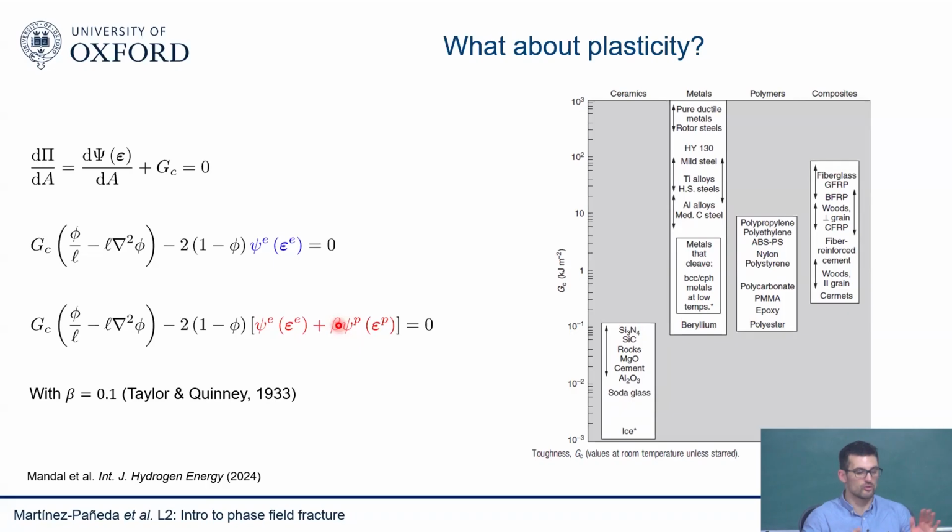So at some point, you may wonder, when does the Griffith energy balance break down? Thermodynamics might always apply, right? You could have a situation where if you have a lot of plasticity, you're heating that area. Then if you want to draw a full rigorous thermodynamics picture, you must build that heat balance into the picture. We don't look into that because we're not looking into those kind of problems, but I agree if you wanted to, you could in principle, because you have thermomechanical calculations where you're calculating where the heat goes and so on. But the only thing we need to know here is what percentage of our plastic work is being stored in the material and therefore it's available. We take 10%, and we believe that this is rigorous with thermodynamics of fracture and so on. I think that's the idea.